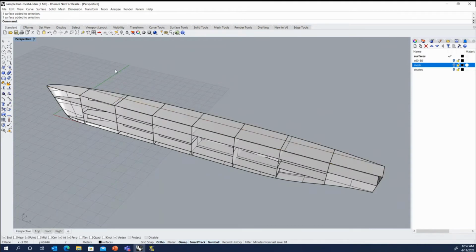Let me start off with the first one. Now, there's a couple methods for creating all of these section cuts that we're going to want. We need a collection of nodes for our mesh, and those nodes have to represent the intersections of all of our bulkheads with our decks and shell plating, as well as the locations of any stiffeners, frames, girders, and so forth, so that we can put the beam traces on the appropriate spots in the mesh.